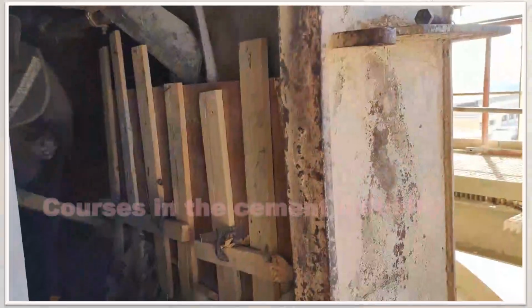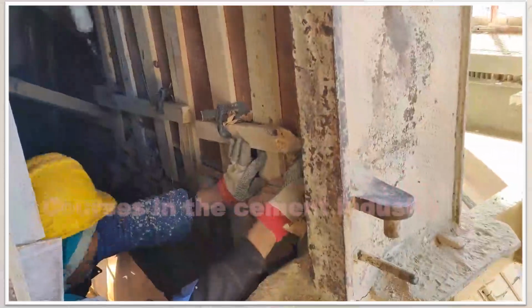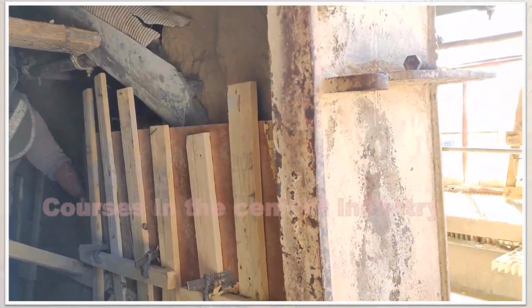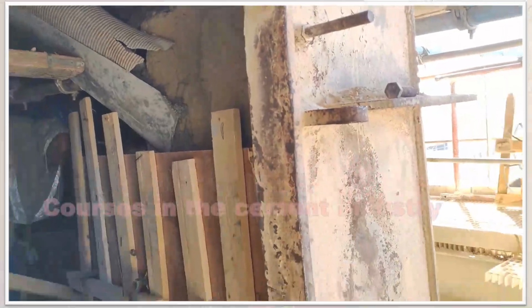The video shows the castable refractory casting method. Castable refractory cement is a dry mix material, so mix it carefully, cast properly, and then dry it completely. It can be shaped into custom shapes, to meet individual requirements.